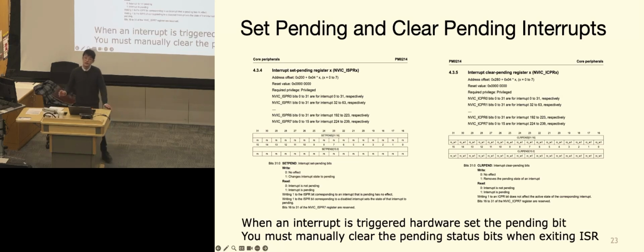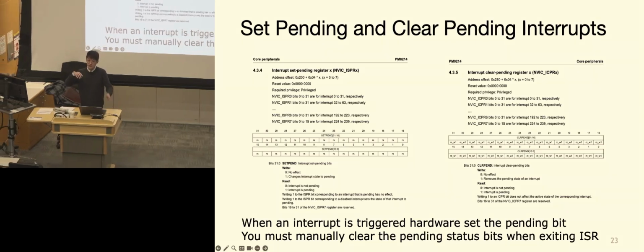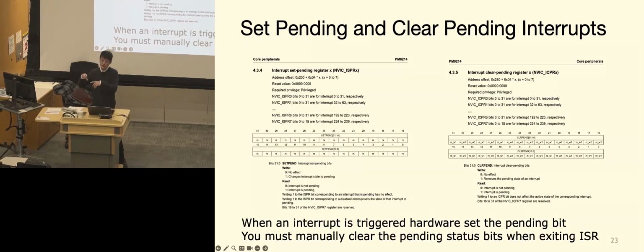No, it will not. After you finish that, or after this is being disabled, you put a 1 into the clear, and that 1 will cause the set enable register to become 0, that 1 bit. So in bit 7, for example, you said that in the set register, you want to set that interrupt, put a 1 in bit 7, for example.